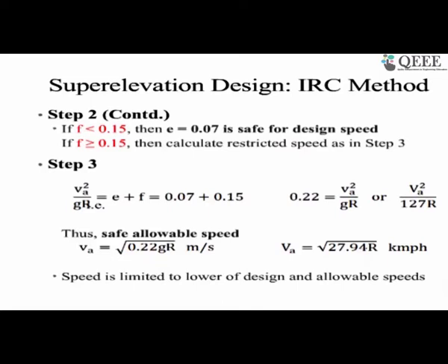Before I move on to the next slide, I got one question, which is: why is the pavement of an airport designed as a flexible pavement but not as a rigid pavement? As a matter of fact, some airport pavements are designed as rigid pavement as well. However, mostly it is designed as flexible pavement because flexible pavements are easy to maintain, first of all. If there is any damage, you can just take out that portion and do the maintenance, whereas concrete pavement is difficult. You have to saw cut and do it and then make sure the level is proper. That becomes a lot of headache.